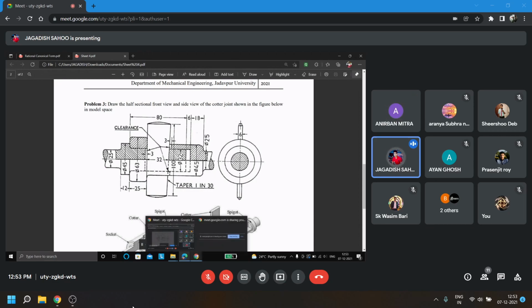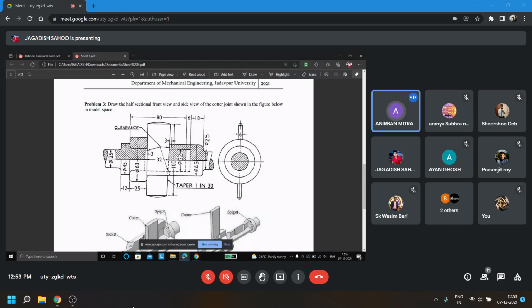হ্যাঁ, কিন্তু স্যার আপনি যে স্ট্যান্ডার্ড হিসেবে দিয়েছেন, ওর রুল কি বলে, মানে মাঝখানে লিখতে, স্ট্যান্ডার্ড ডাইমেনশন ফলো করতে বলেছেন? না না, মাঝখানে লিখতে হবে সেটা নয়। তুমি যদি এখানে মাঝখানে লেখো তাহলে it will overlap with the হ্যাচিং পোর্শন, হ্যাঁ রাইট? হ্যাঁ, বাট একটা জিনিস মনে রাখবে যে আমরা কিন্তু কনভেনশনালি পার্টের মধ্যে ডাইমেনশন দিই না। We try to provide the dimensions outside of the part.